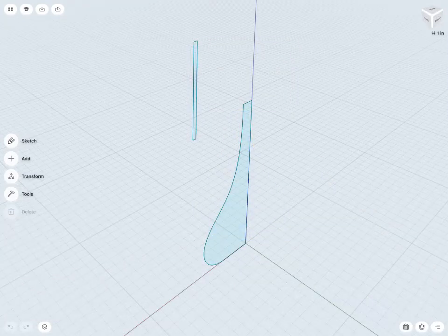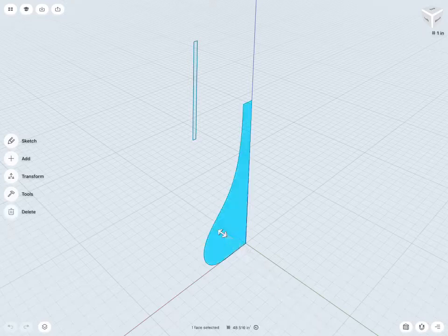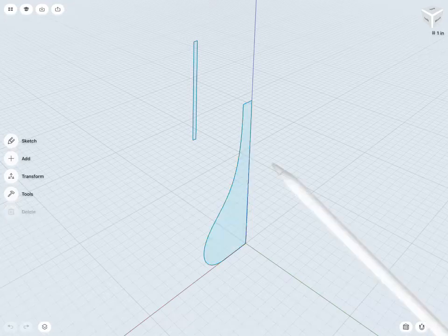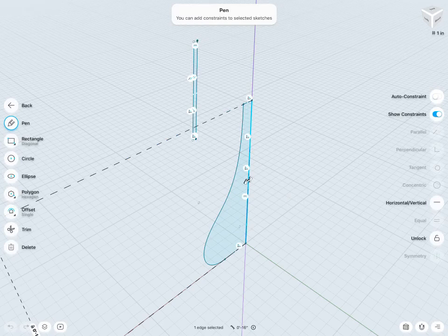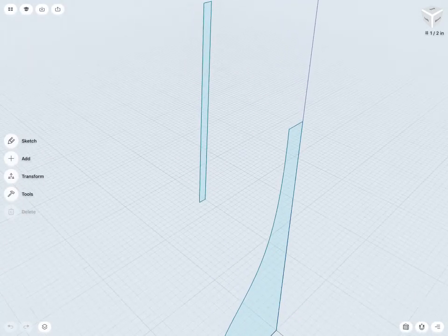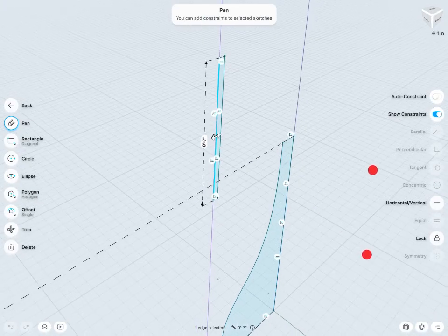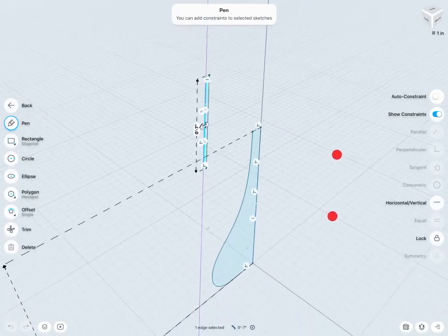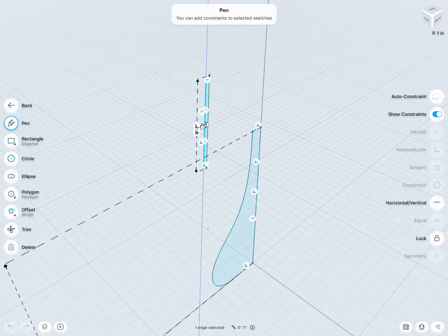To generate this 3D model of my lamp design, I've started off with a sketch like this for the lamp base. Essentially what I'm doing is revolving that 360 degrees about some central axis, in fact, this axis right here. Same idea for the lampshade: I have my lampshade sketch, and again I'm just revolving it all the way around that Z or purple axis we're seeing here.